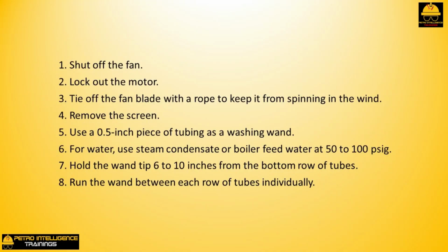1. Shut off the fan. 2. Lock out the motor. 3. Tie off the fan blade with a rope to keep it from spinning in the wind. 4. Remove the screen.